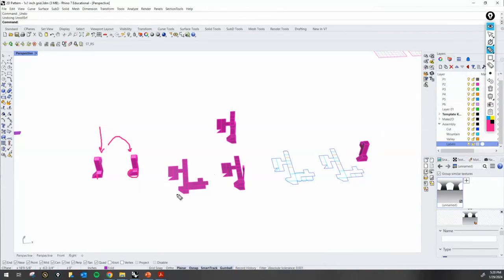And then we're going to go through a process of unfolding that 3D object into first surfaces, as you see right here, but then onto lines, and we're going to develop a legend or a key for the constructing mechanism. Talk more about that, and then we'll also look into adding tabs so that we can actually end up with the template that we can actually use to fabricate, or in this case, create your model.